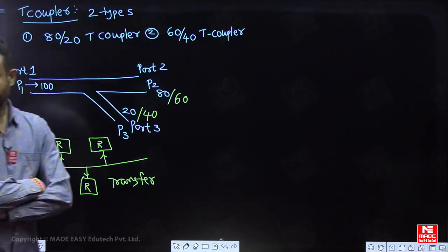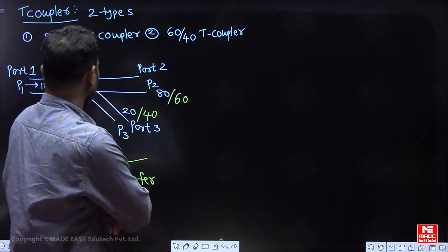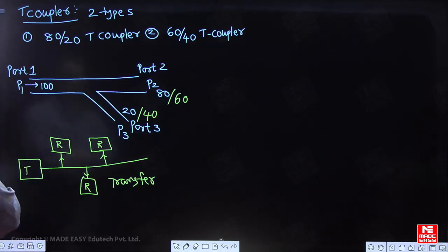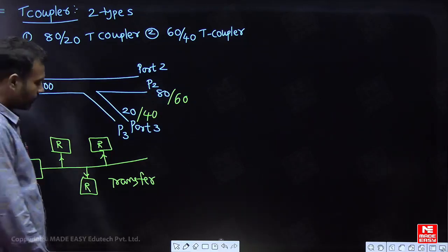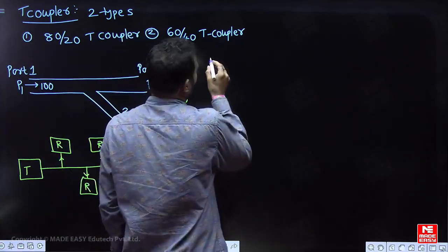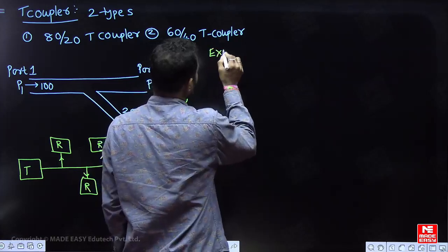So next important thing after this I will explain to you. Another one is nothing but the losses. So the first loss that we are calculating here is called the excess loss, and we are also calculating the remaining part of the losses. I can explain you about all the losses. What is the excess loss, insertion loss, directivity or crosstalk. So please see here carefully. Explaining you about the first loss called excess loss.